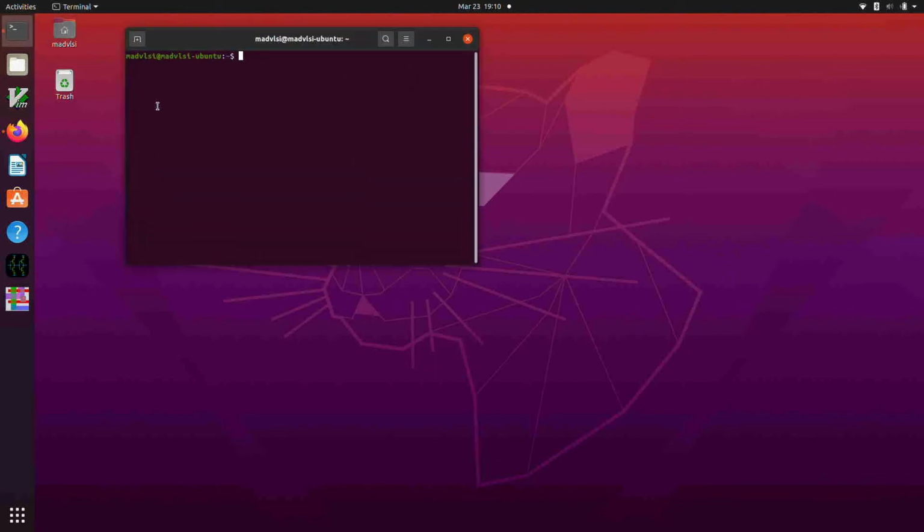So the setup for Monte Carlo simulation is going to be very similar to the one that I went through for the Skywater 130 technology in the NMOS 01V8 and the PMOS or PFET 01V8 and the NFET 01V8. So it's the same style of setup.